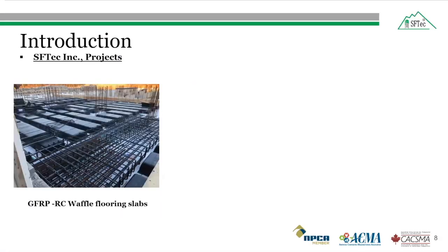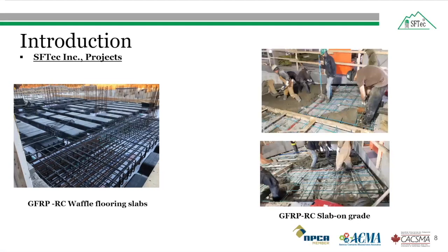Here are some selected field applications of the SFTec fiber reinforced polymer bar we have already done in Canada. The glass fiber reinforced polymer reinforced concrete waffle flooring slabs designed with SFT glass, which was built in Halifax, Nova Scotia. And it can also be used for slab on grades. It is a non-structural slab, so it is a one-to-one replacement and saves a lot of money compared to the steel bar in terms of labor and transportation.